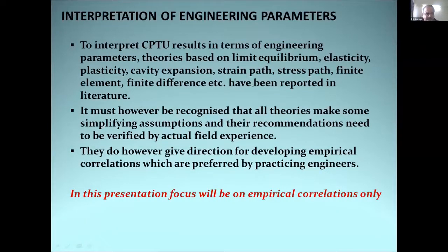So coming to CPTu interpretation in terms of engineering parameters, a number of theories have been used for interpretation of CPTu results, like limit equilibrium, elasticity, plasticity, or cavity expansion, etc. It must, however, be recognized that all theories make some simplifying assumptions, and their recommendations need to be verified by actual field experience.